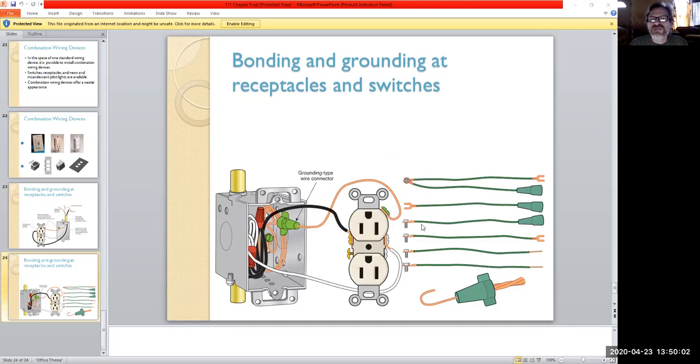so yeah, we look at the bonding styles, right? And again, you want to be careful when you do ground, and it's going to be a bare wire. And this is a neat little thing, see how the wire connector actually has the pigtail built into it already. You buy them this way. It's actually a time saver. That way you bring your grounds in, you got splices going on, right? So you can bond them all together here and still have that single pigtail coming out to go on your receptacle.